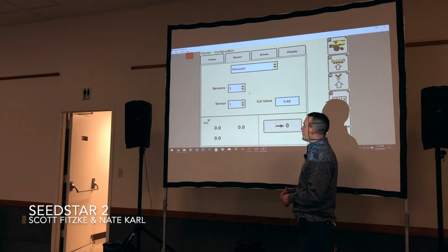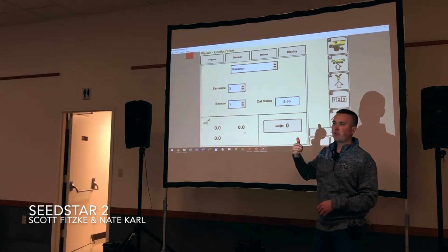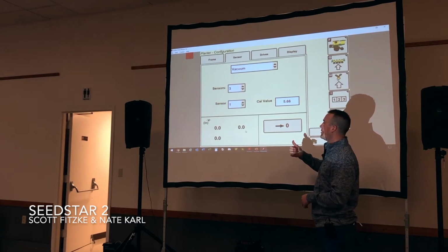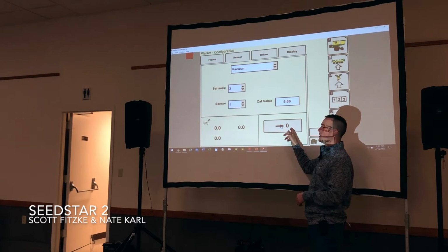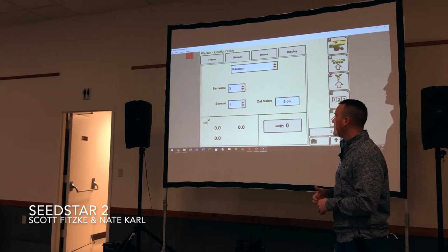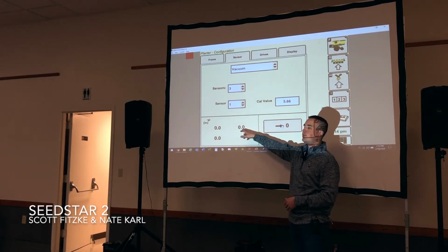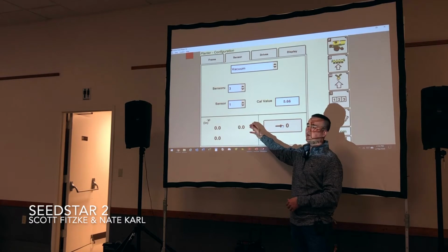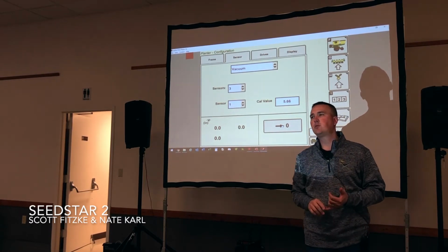Down here in the bottom, we see the indication of all three sensors, kind of like we had on that main run screen. Down here, to the right of it, we also have an arrow that points to the right with a 0. This is our reset button. Anytime we see a number sitting stagnant, bouncing from 0 to 0.1 or 0.2, but we don't have the vacuum on, we're probably having an issue with that sensor.